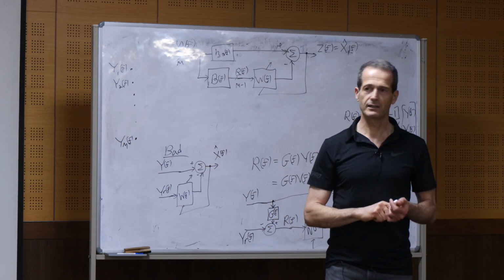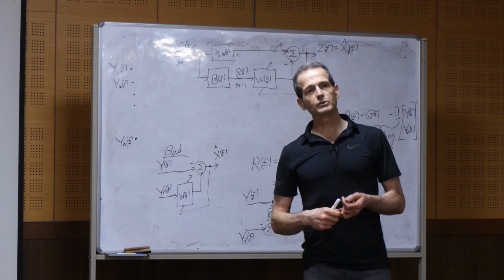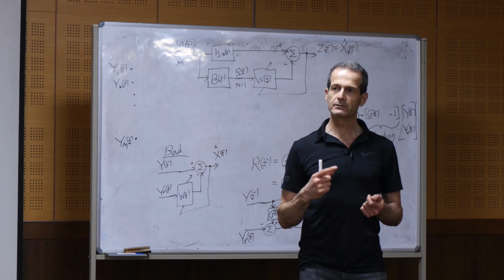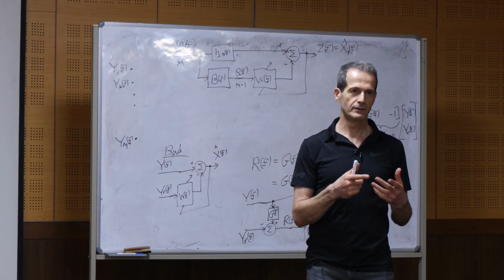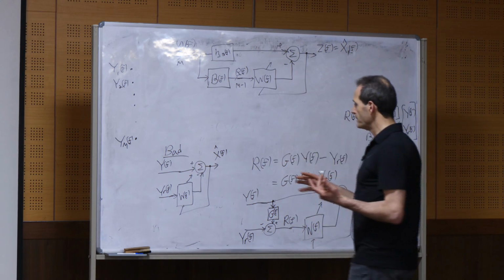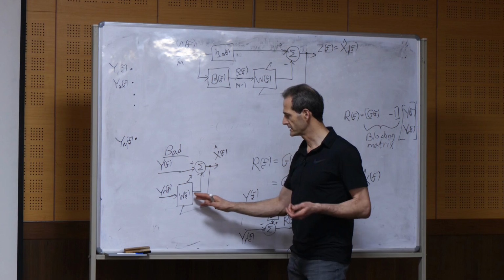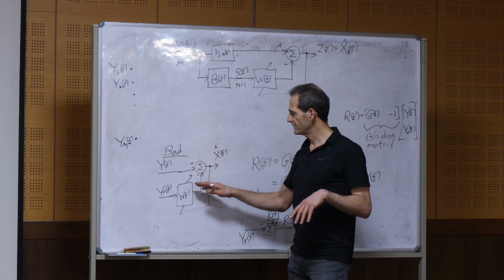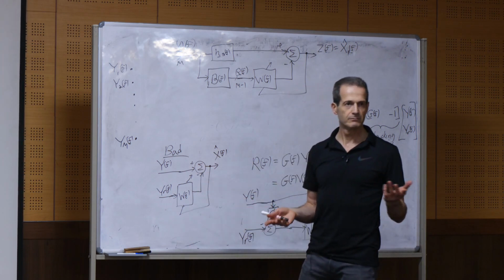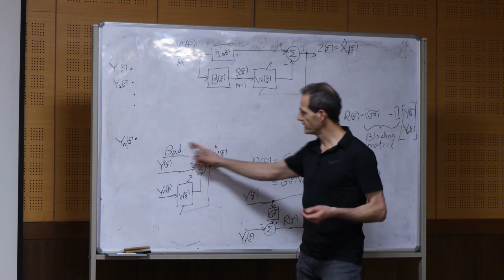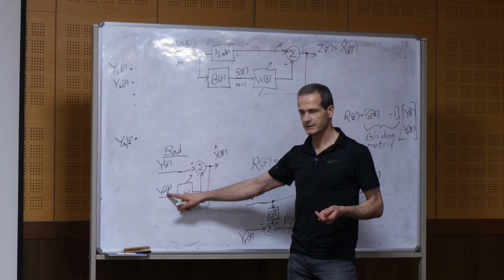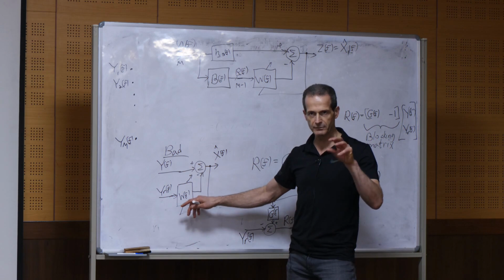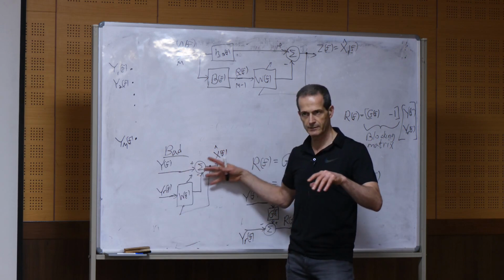Exactly, the mother's heart rate. So what do you need to do? You can add another sensor, another microphone, and put it next to the heart of the mother. So maybe it will have only the reference, only the heart rate of the mother, and the heart rate of the baby is negligible. Okay? And then what you need to do is something like that. So if the other reference signal doesn't contain the heart rate of the desired signal of the baby or the fetus, we are good with this solution.